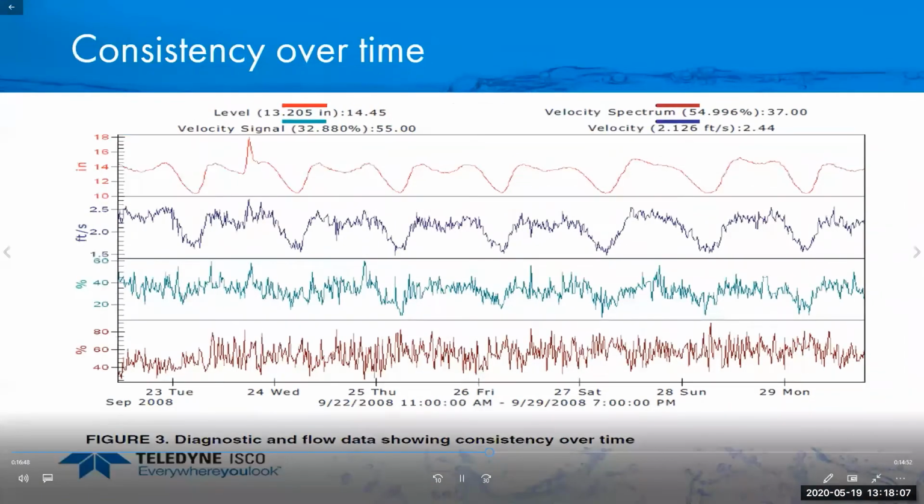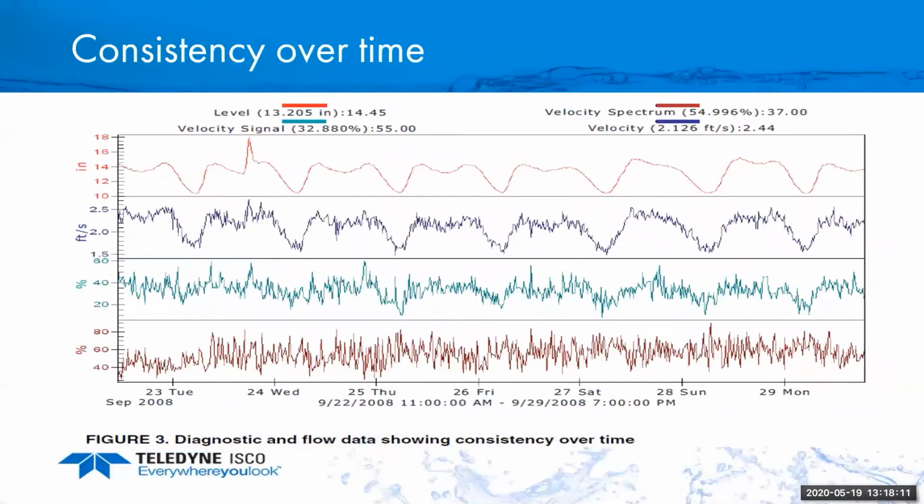Depending on how clear the water is will determine the signal and spectrum. So what I'm looking for is that over time, I'm remaining consistent with these readings. If I would see that the signal and spectrum would start to degrade or drop, that would be my indication. That's when I need to go out and inspect the site and possibly clean off debris.